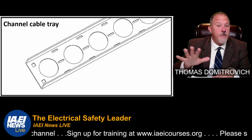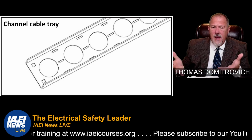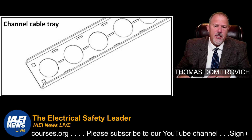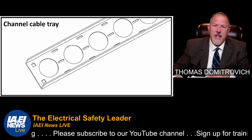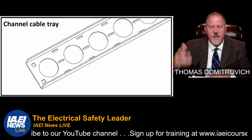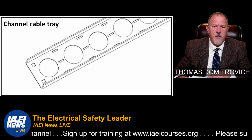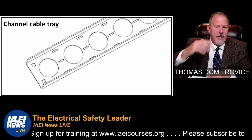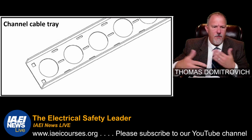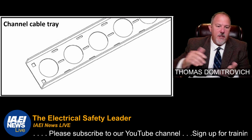For smaller instrumentation cables, these are typically 3, 4, and 6 inch widths, somewhere in that ballpark. Channel tray is for smaller instrumentation cables. It's an effective alternative to large conduits for supporting cable drops from the main cable tray.